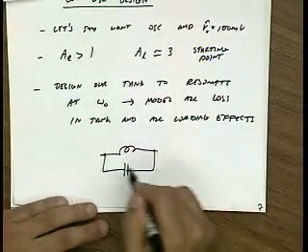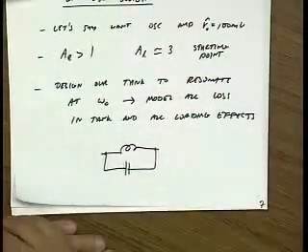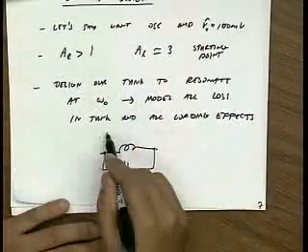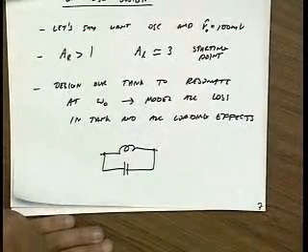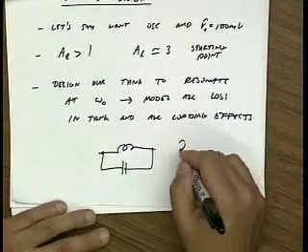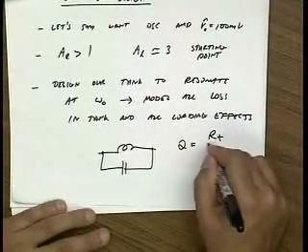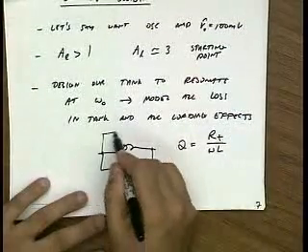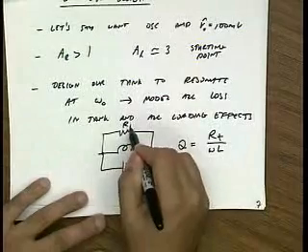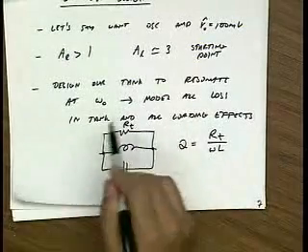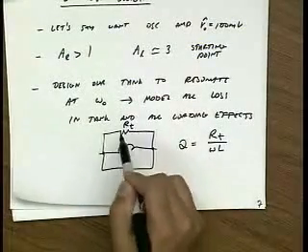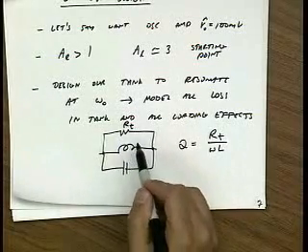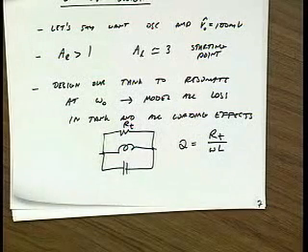And so obviously if you're going to drive a load, you have to buffer it. Let's say it's a 50 ohm load, you're not going to put 50 ohms across here because that would de-Q your tank. Remember, the Q of the tank is RT over omega L. And so what you'd like to do is maximize this shunt resistance. In fact, you'd like to not even put any explicit resistor here. Just let this be the total parasitic resistance of, say, the inductor and capacitor combination. Okay?